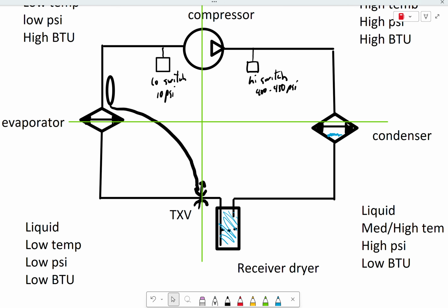Okay. And then what happens is we're not pumping any refrigerant in the system, so any of the refrigerant that's sitting in the condenser as a vapor, we're actually going to start stripping more and more heat out of it. There's going to be more subcooling. And as you start pulling heat out of the refrigerant, as it starts to cool down, what happens to its pressure? It goes down. Okay? It's really interesting that a blocked expansion valve does not cause higher than normal high side pressure. It actually causes lower than normal high side pressure. Okay?